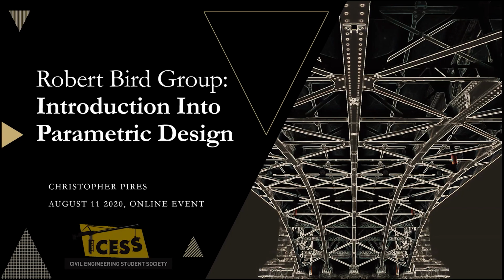The engineer might not even know the plate thickness requirement yet, but you could set a parameter and have it at 50, 100 mil. And once the engineer has confirmed the plate thickness, you could update it in Grasshopper and Rhino and then bake the model, and it's already generated everywhere that connection is typical.